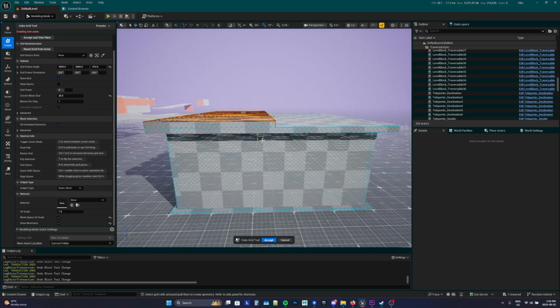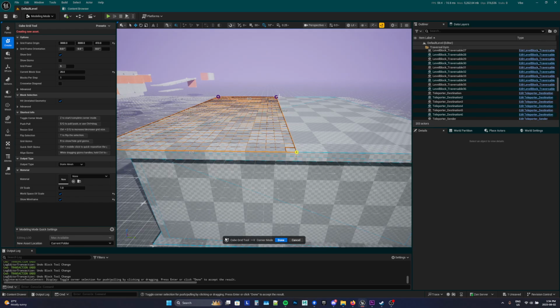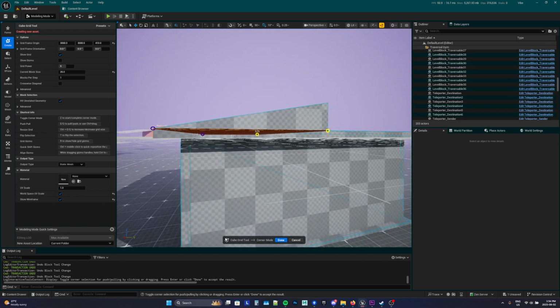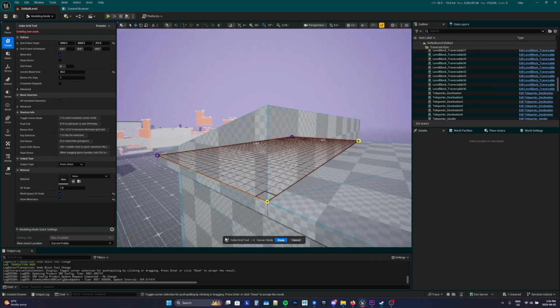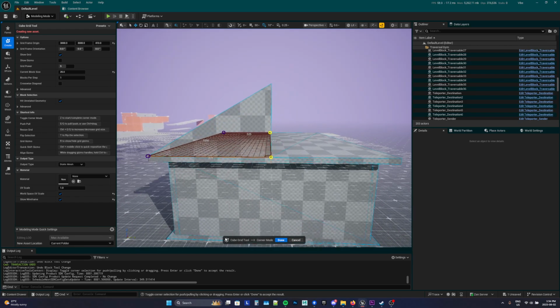Now, instead of lifting up the whole thing like this, what I want to do is I want to hit Z. Z toggles corner mode right here. And when I'm in corner mode, I can select the corners that I want, and I can use the same Q and E to push or pull my geometry. Oh, that was kind of hard to see there. So if I push it up, it's just going to go 1 up. The nice thing about this mode, it doesn't add extra cuts as you push or pull. So that's kind of nice.